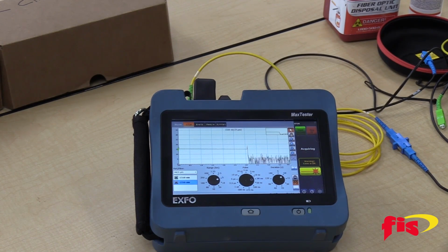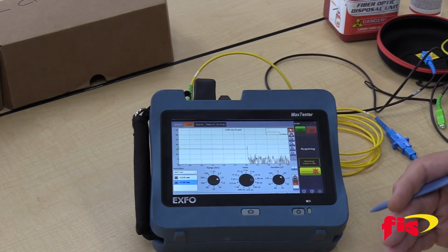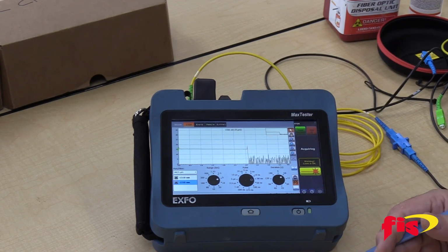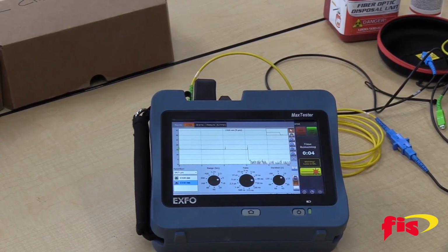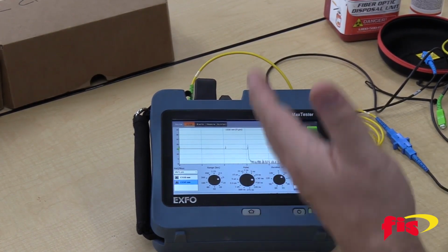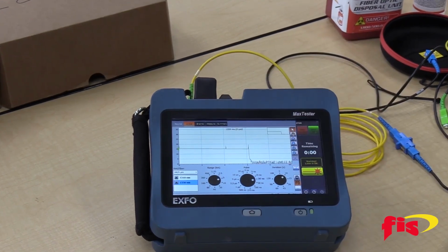All right, so our launch cable has to be longer, in my opinion, than the biggest dead zone that we have. And again, I'm going to use 100-meter ones here because I've got a 3-kilometer box, so it's not a big deal. So I'm going to go back and actually do a test here. This is going to show you the problem of not being able to test the first and last connection. So I've got my test cable plugged directly into the OTDR.